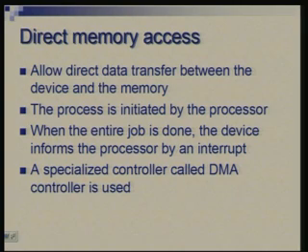A DMA controller could take care of not just one peripheral device, but multiple peripheral devices which are required to transfer data directly to the memory. So, it could be a 2-channel DMA or 4-channel DMA. A 4-channel DMA, for example, would allow 4 high speed devices to transfer data to memory or read data from memory.